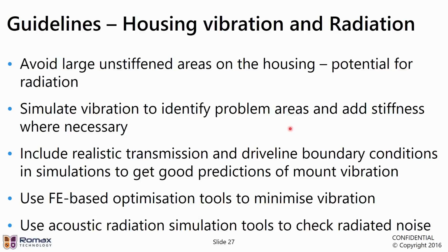I mentioned this before, but you need to make sure that you include the boundary conditions for the transmission and driveline in the simulations, so that we get good predictions, because one of the things we're interested in, of course, is vibration at the mounts, because that is what transfers vibration to the rest of the structure. And therefore we need to have a representation of how the transmission is mounted in our model.